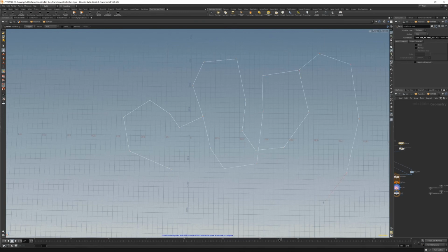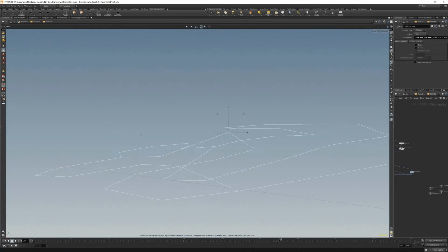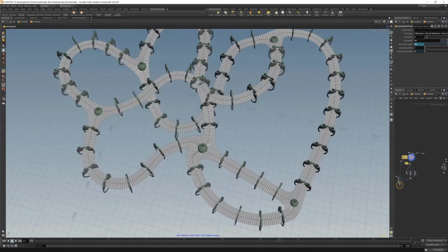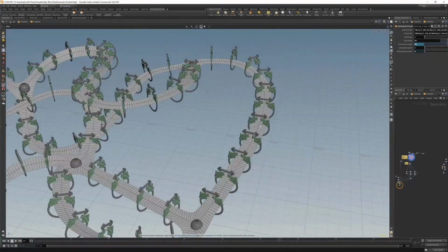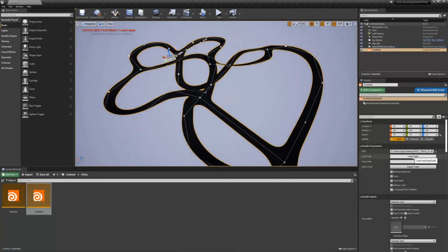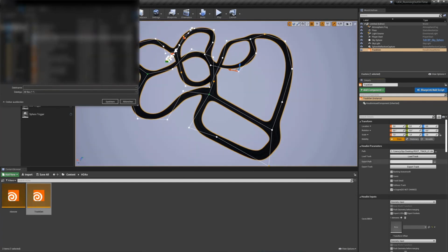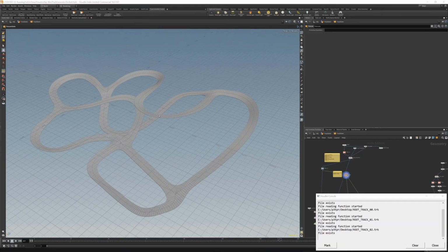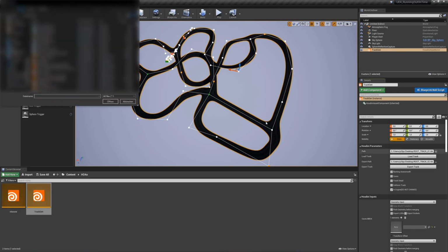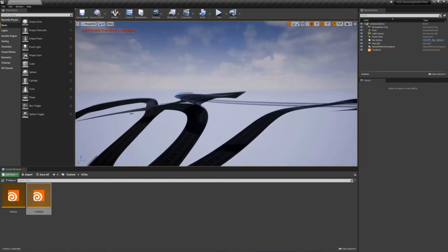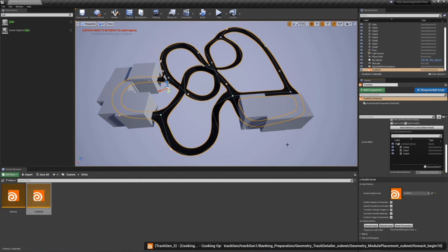This is a sped up video of the track creation process from start to finish. Here, shelf tools are used to navigate the network and edit these curve nodes. Then, the viewer state shown before is used to change intersections and banking of the track. Now in Unreal, small changes to the track are made and saved to a JSON file. This is then loaded back into Houdini, where the user proceeds with adding fences. This is again saved in the JSON file and loaded back into Unreal. As a final step, bounding boxes are used as input for placing procedural caves and arches.